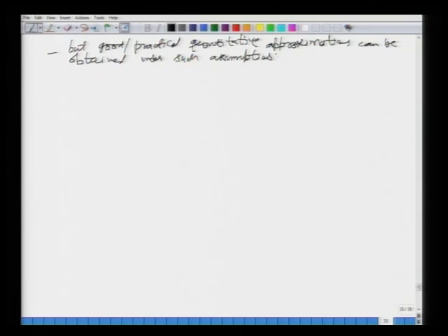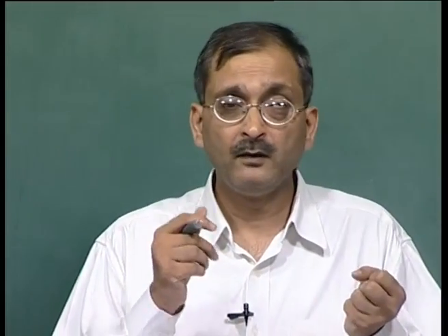So, what we have done today is we have looked at some other aquifer properties in terms of the specific yield and specific retention, and then we looked at an example, and then we looked at different types of aquifers, mainly confined and unconfined. There are various intricacies, the properties, and how they behave when they are subjected to either pumping or different types of forcing functions. All of this is important to understand, and towards the end we have seen what an idealized aquifer is. In the next class we will look at how we can handle anisotropic aquifers, in which we may have different layers, and how we can model that.